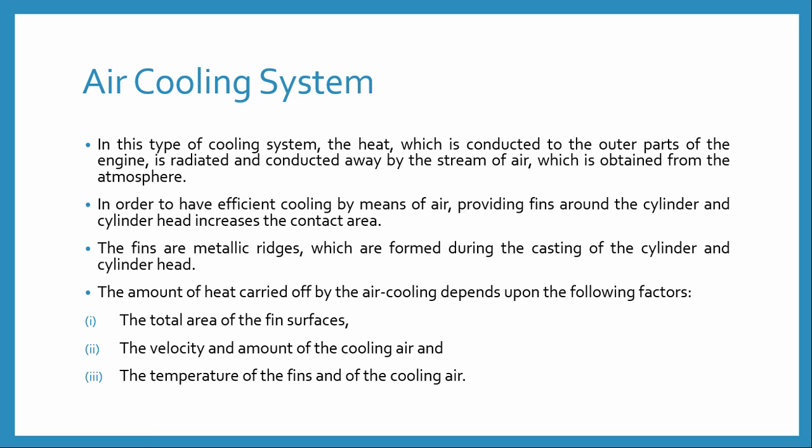This type of cooling system is mostly employed in light engines such as motorcycles and scooters. The heat dissipated depends on a few factors. First, the surface area of the metal which is in contact with the air, here the metal is called the fin.